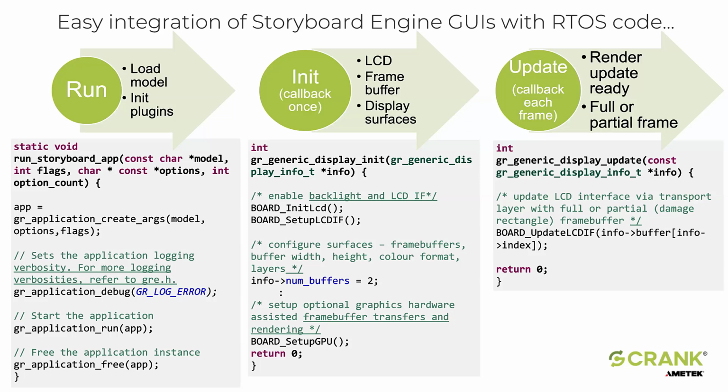So that's done once. And very simply, every time a pixel changes subsequently, another function which you implement, and this is all your code, very simple, is do whatever you need to do to take the frame buffer and copy that to display. So the generic display update is called every time a pixel is changed.